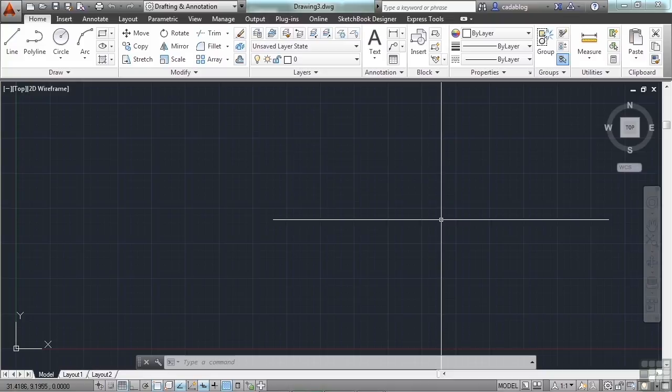In all honesty, you could use a regular DWG file as your template if you wanted to. Just open it as you would any existing file and have at it. The danger with doing that, though, is that when you save the file, any changes made, well, they'll be saved to your template. And so the next time you go to start a new file, you may have project-specific information in there, or maybe there's something missing that you deleted because for your drawing file, you didn't need it. So try not to do that.